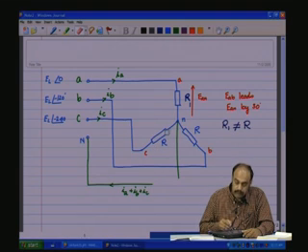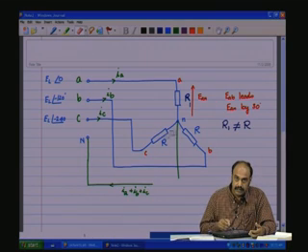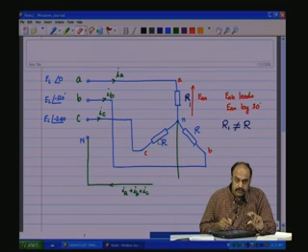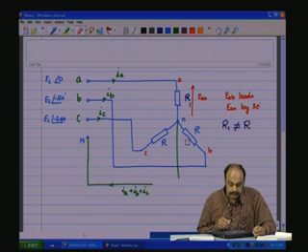So, it is not purely IC, which was in the case of the balanced load that would be flowing here, and IB. There will be a part of IA which will get mixed into IC, and a part of IA gets mixed into IB, and those changed magnitudes of IB and IC are going to get multiplied by R and get reflected as the voltage drops. So, the voltage drops in this phase will now change.